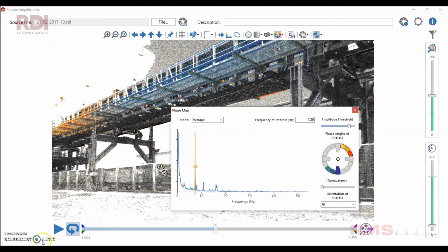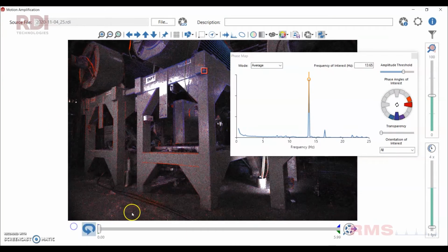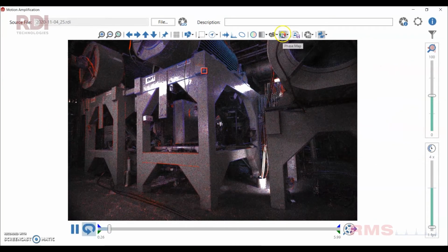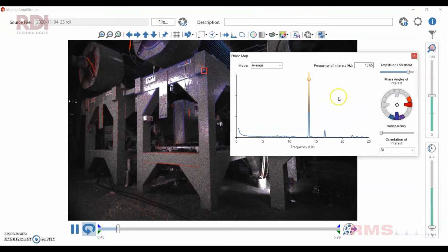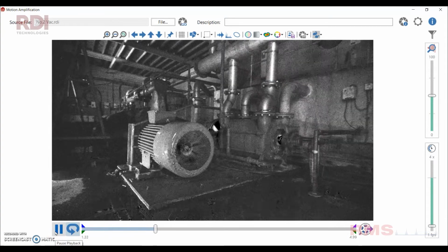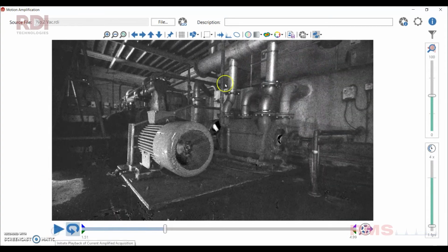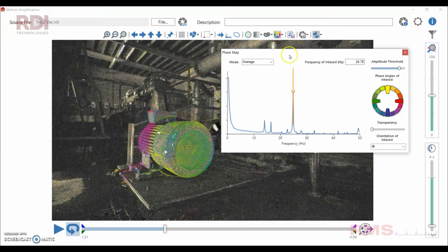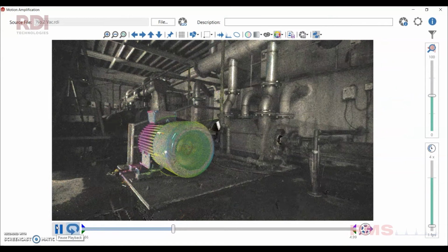Really, really nice tool, very visual. Here's a couple of examples. These are 90 degrees out of phase, these two components. And again, I've just highlighted those frequencies and it overlays that color. Got another example here. This is a motor rocking due to a base problem. And you can see when we overlay that, real contrasting colors there. 180 degrees, drive end to non-drive end rocking there. And if you add a bit of transparency, you can even show a bit of the motion in the video.